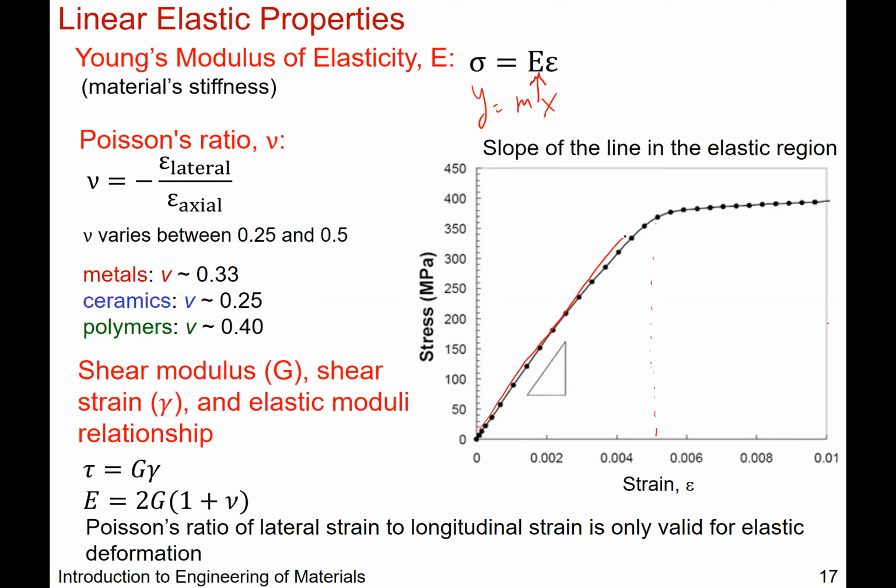So you must wonder, where does this line end, right? Where do we consider the elastic region, and where does it stop, so that we go on and enter the plastic region, where deformations are not reversible, okay, where you're starting to break bonds and reform bonds. We'll talk about that, but for now, let's just assume you can eyeball some linear slope like this. Okay, so it's just rise over run, stress over strain, sigma over epsilon.